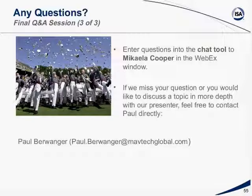You don't want it to. Typically, if you don't require an operator action on something, it's not an alarm, right? And so you don't want it to make a noise. You want it to just go to a journal and let it be there. Now, having said it, this goes back to the batch question. Yes, you will have alerts for certain situations that come up, and this is on a case-by-case basis. But typically, alerts are not audible. You just want them going to a journal.